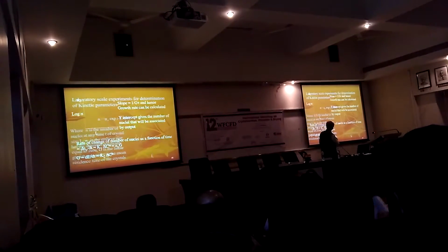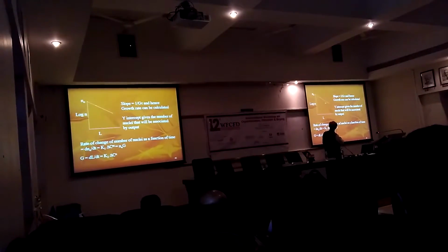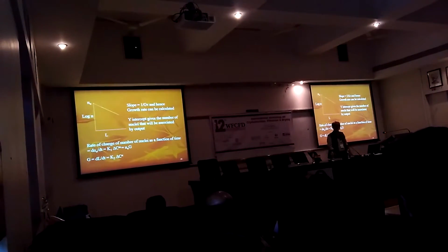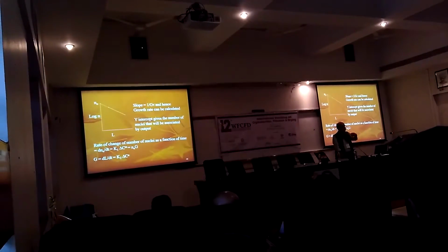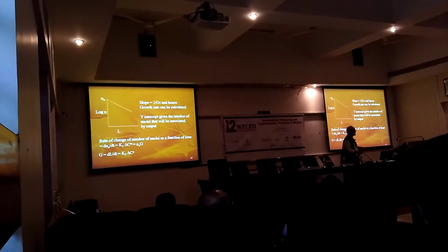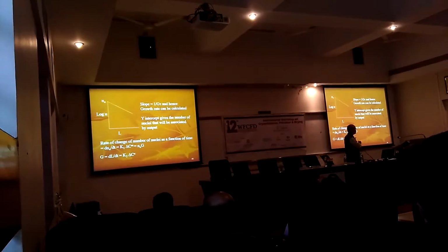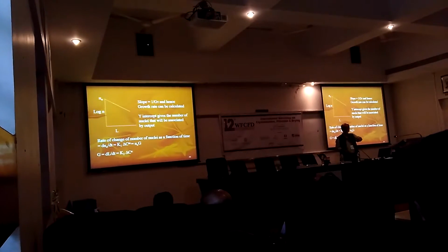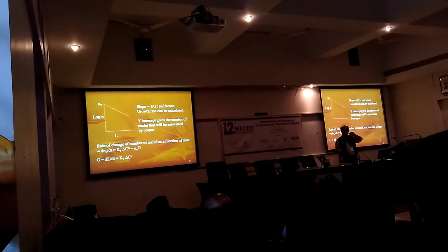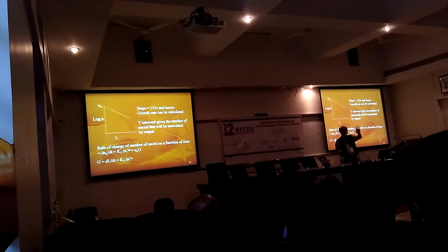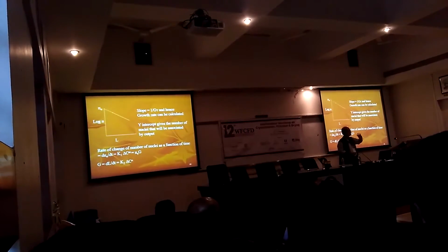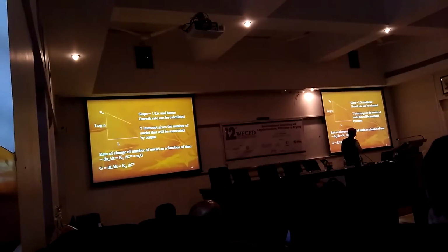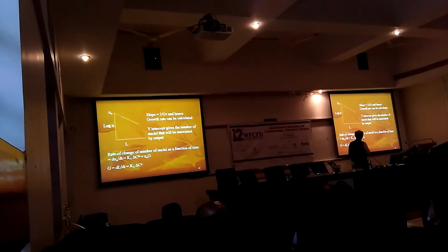Now if the same graph can be extended and I extrapolate it for practically zero size. Practically zero size means what? Nuclei. Right? They have just spontaneously come out in the solid form. Now this N naught, as a function, if I can get at different states, I can estimate the nucleation rate. Nucleation rate and growth rate, as was pointed out by Mike, are going to be proportional to supersaturation. So the degree of supersaturation will decide the nucleation rate as well as the growth rate. So you can get this information by conducting simple experiments, and we'll see this in detail.